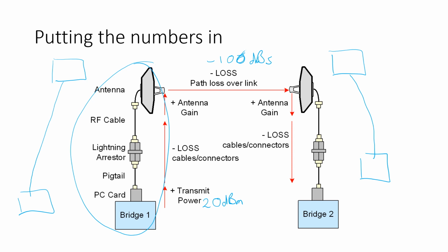It depends on regulations at the particular point in time, and there are signs of some new regulations coming out which allow us to transmit more power on external links. The antenna gains for the internal antennas are plus 14 dBs in both cases. And our receiver sensitivity, at this end, is minus 96 dBm.